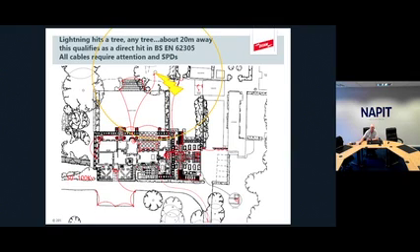Now, if I only had one SPD at the origin, if lightning hit anywhere, let's say that tree, there would be a very large increase in ground potential, maybe a couple of 100 kV. And as we get further away, that could be maybe 50 or 100 kV. So every cable in the ground is going to bring into this installation an induced current.